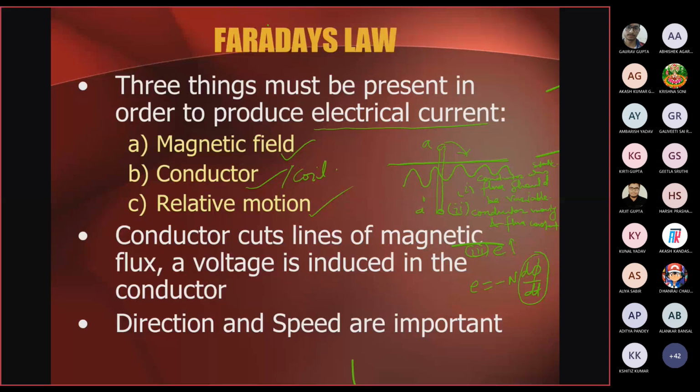Later on you have to study single phase transformers. So you know that transformer is a static device. So in that condition you will see your conductor will be static but flux will be time varying. So first condition will be fulfilled, right? Now in case of DC machine, when you will study DC machine in this syllabus later on, you will see that your conductors are moving and the flux is constant. Flux is constant due to the DC supply. Your flux will be also static in nature, but we are rotating the conductor. In that condition you will realize the second condition, right?